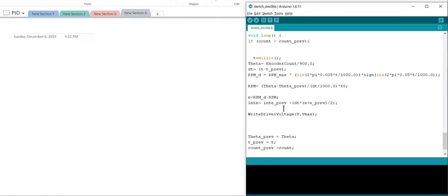And this is the integration variable, the integration error variable. So this is the same thing as what we calculated in the beginning of the video. See the integration error previous, which is just the integration error k minus 1, plus using the trapezoidal method. And all this error will basically be the summation into a voltage variable.